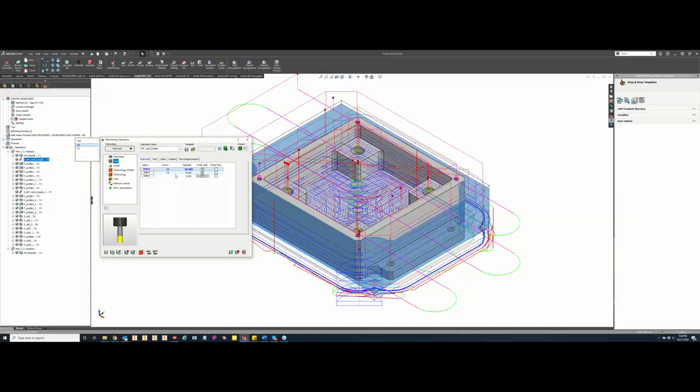I guess it all depends on the material that you guys are cutting. On a particular part like this, we're cutting 1018 cold rolled, going from a 20 millimeter to an 8 millimeter. I'm not going to worry about that at all, because, like Greg was saying before, iMachining is not just going to do one finish cut with that 8 millimeter. It knows what material is still left over, and it's going to slowly approach that material and get it out of there.